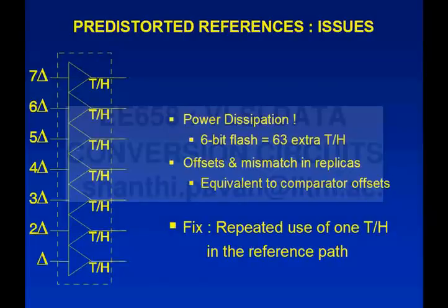You're going to be auto-zeroing that preamp one at a time, which means that the reference and the offset are stored on those input capacitors, and since charge is not lost from those capacitors, you can come back and do this for this particular comparator a long time later. There's no need to do this every clock cycle, which is something that makes sense even from a flash speed point of view, simply because that time is now available for conversion.